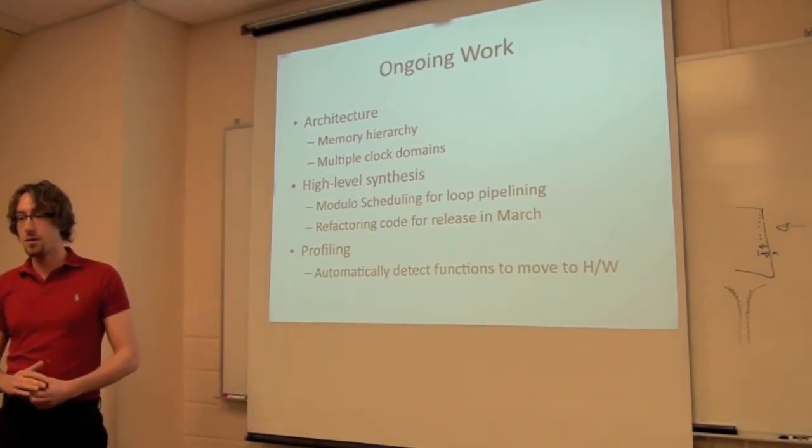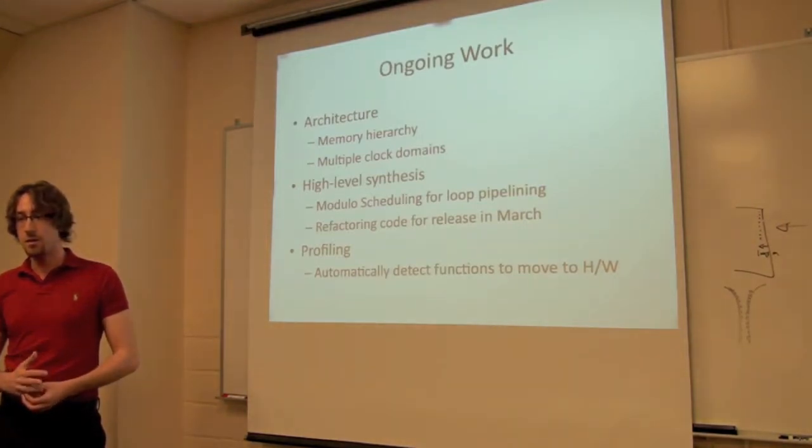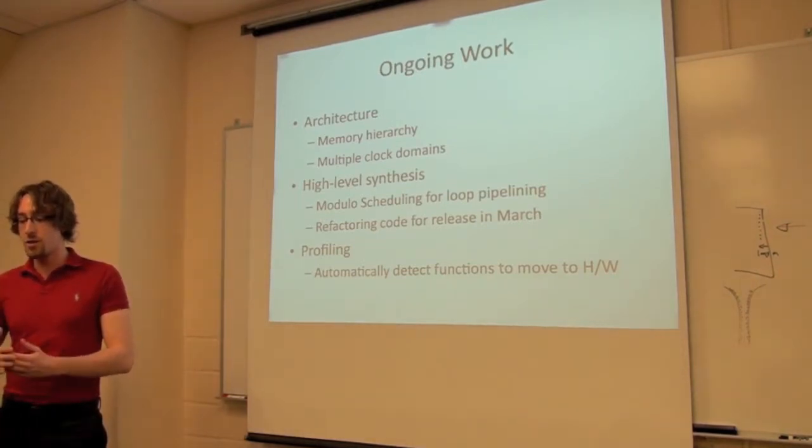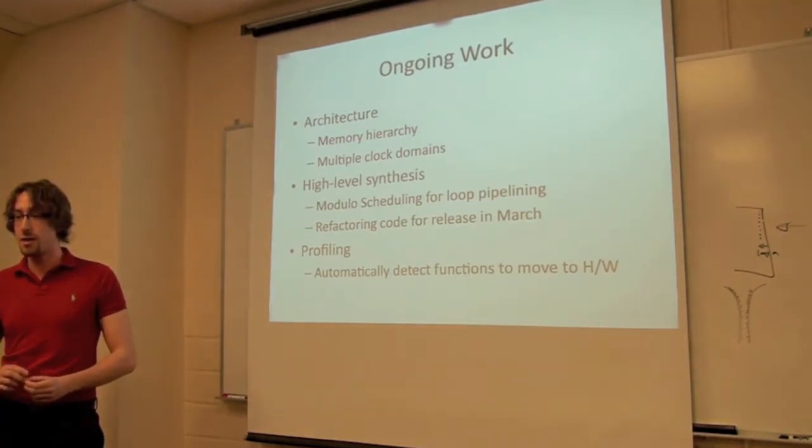But it doesn't matter given the area numbers you have? Exactly. There's a register for each LUT too, so it's kind of free. I think they focused a little bit more on sharing registers. But when you share registers, you now have a mux in your clock period, so it's not really worth it in my opinion, at least at this stage.